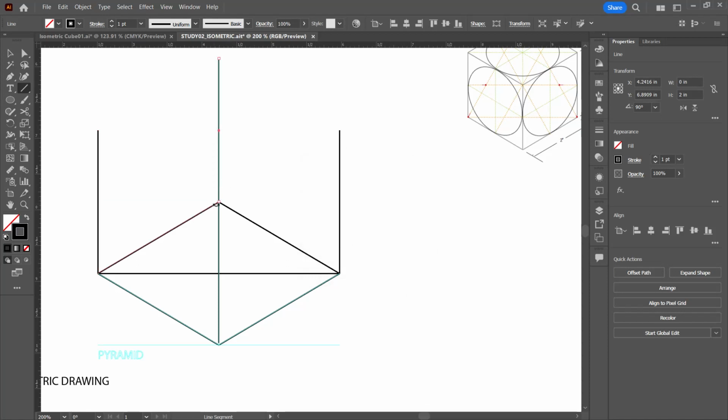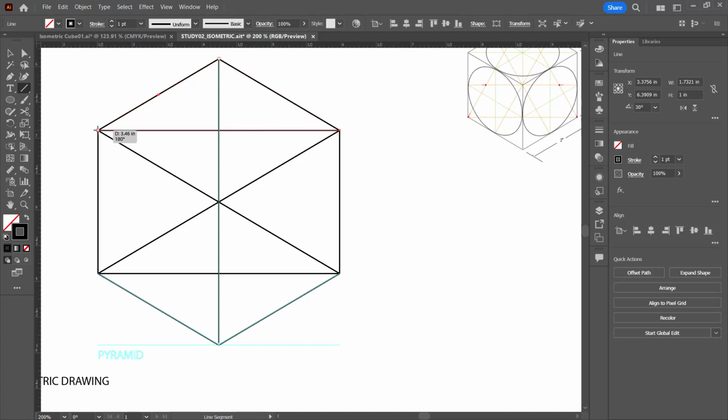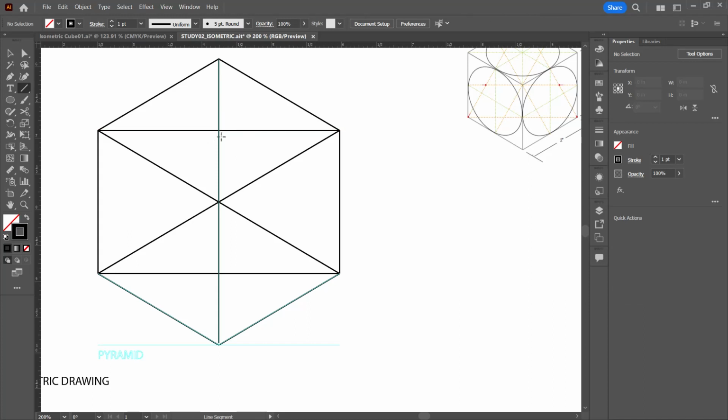And so we could just click here and do our 2 inches. All right, so then this would be our top. Come in here, draw, boom. Right, this is our top of our cube. And if we do our little cross here, our little bisection to figure out where we are, now we could come in here. This would be our center point of our cube. So if we come in, go back to our deselect everything, that's our center point.